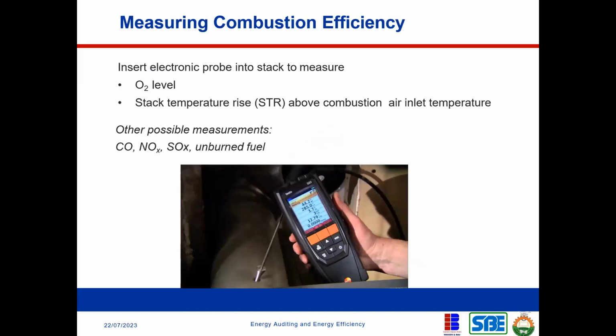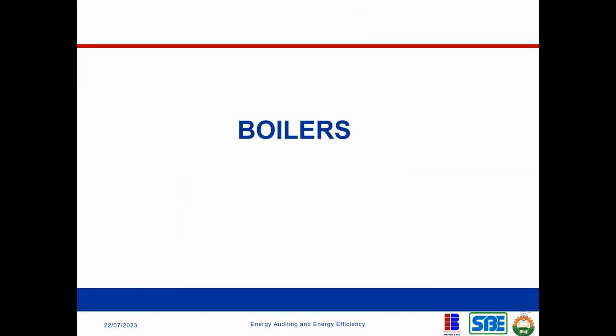Like I already mentioned before, to measure the combustion efficiency, you need what we call a combustion analyzer. Here is a picture of a combustion analyzer. It will tell you if there is complete or incomplete combustion. If you notice the presence of carbon monoxide, nitrous oxide, or sulfur oxide, all of this is an indicator of incomplete combustion, but chief of them is carbon monoxide. It tells you that there is fuel that is not being burnt in this process, so it does not achieve complete combustion.